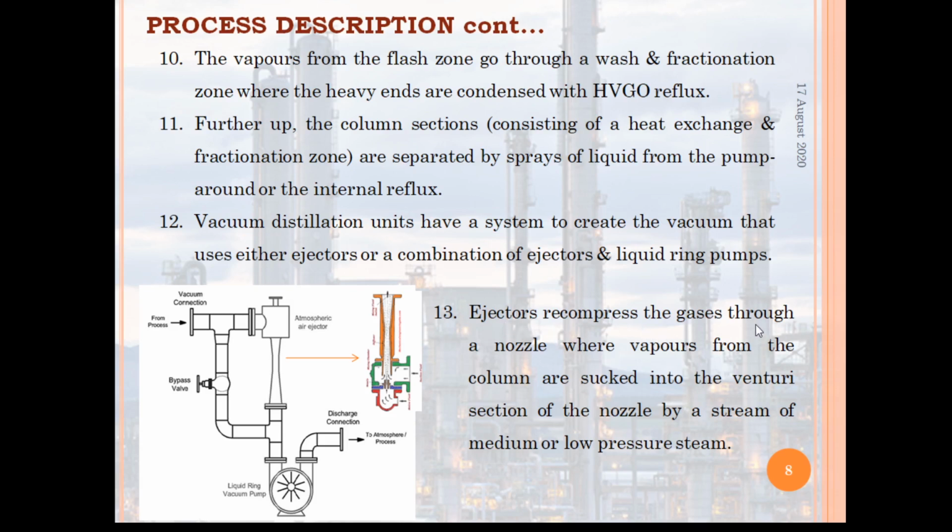So these ejectors recompress the gases through a nozzle where the vapors from the column are sucked into the venturi sections of the nozzle by a stream of medium or low pressure steam. So we know the venturi principle from fluid mechanics.